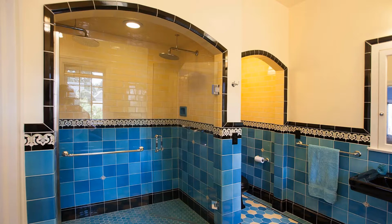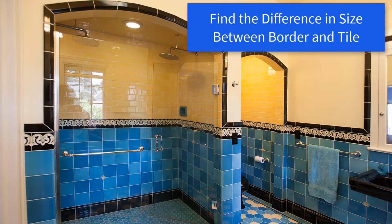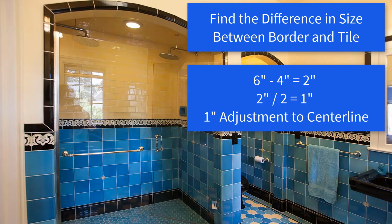The mathematical way to determine the cut size when a decorative border is specified is to find the difference in size between the tile and border. In this case, 6 inches minus 4 inches equals 2 inches. Then divide the difference by 2. The center line or start point vertically will be adjusted by this measurement.